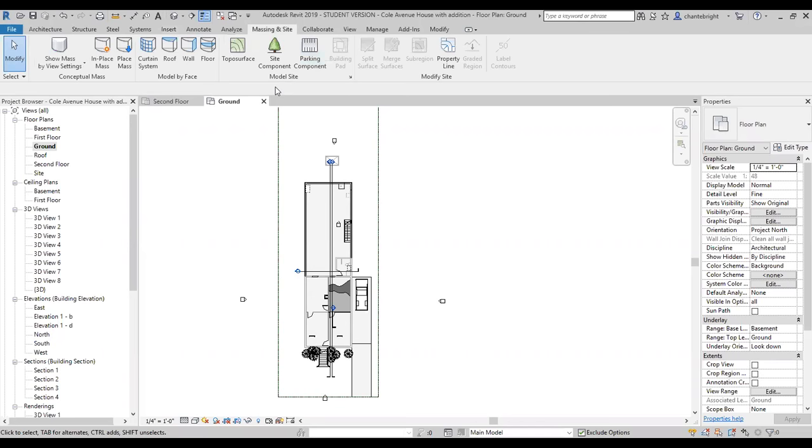One thing to keep in mind when doing something like that is you are triangulating your points. In other words, you need 3 points in order to create a surface inside of Revit. And a topo surface is a Civil 3D thing. What I like to do is pull in an image from behind to use inside of my model, so that I have some idea of what the surface is supposed to look like.